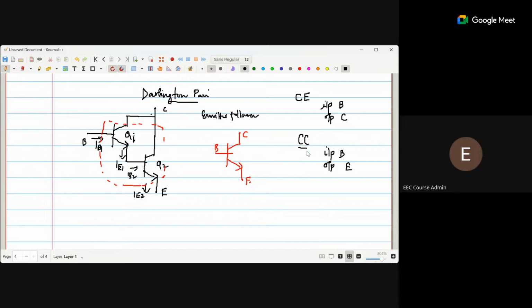Yes, we haven't seen it, I also think. Here, tell me, also here two collectors are common, na, ma'am? Correct. That is what this altogether is. It is just like a super transistor with beta, which is the product of these two. And if they are the same, it will just be beta square. So it's just like these two transistors Q1 and Q2 forming this transistor, so that the terminals coming out are base, collector, and emitter.